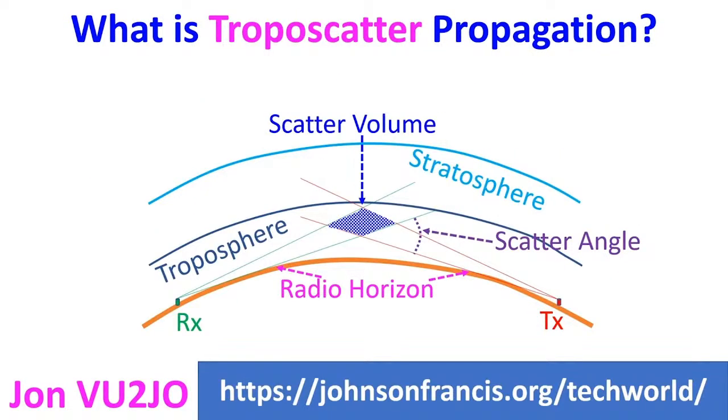Tropospheric scatter propagation is known in short as troposcatter propagation. Troposphere is the lowest layer of the atmosphere. Though troposcatter is typical at microwave or super high frequency or SHF band, it can also occur at VHF and UHF bands. The height of the troposphere is about 20 km near the equator, which comes to about 9 km in polar regions in summer. Height of the troposphere is more in summer than in winter.